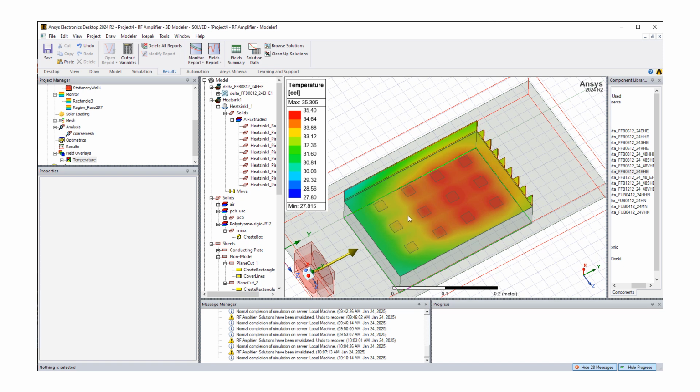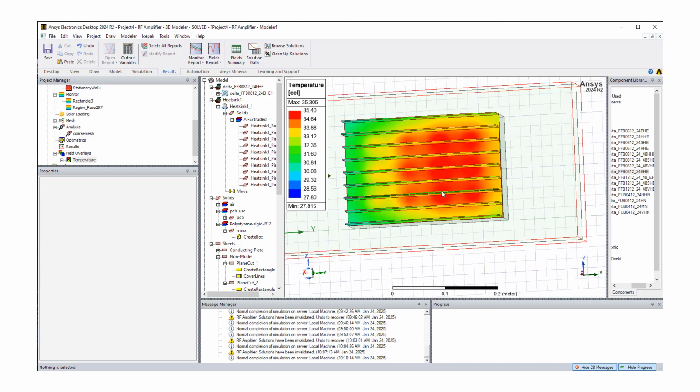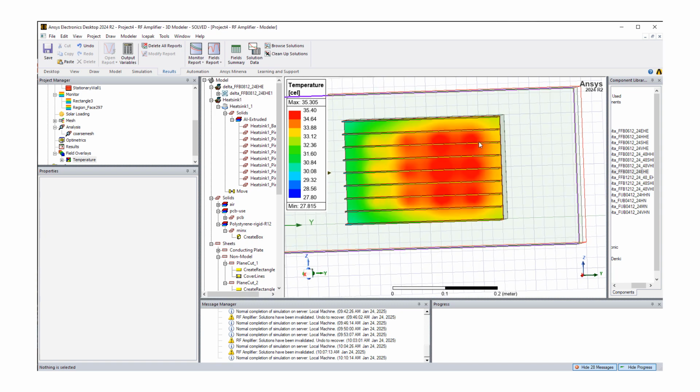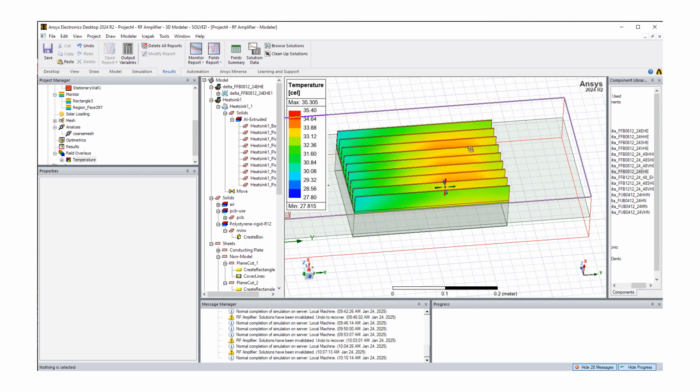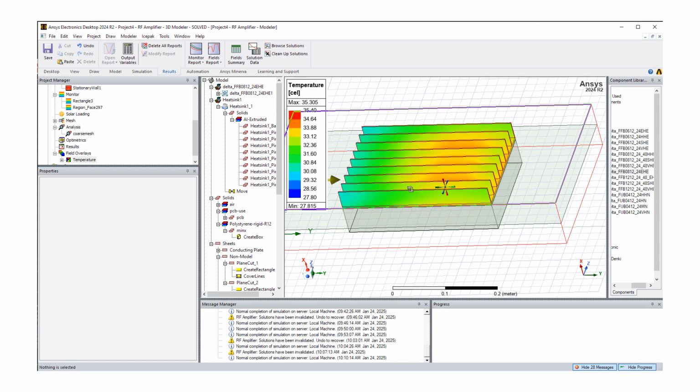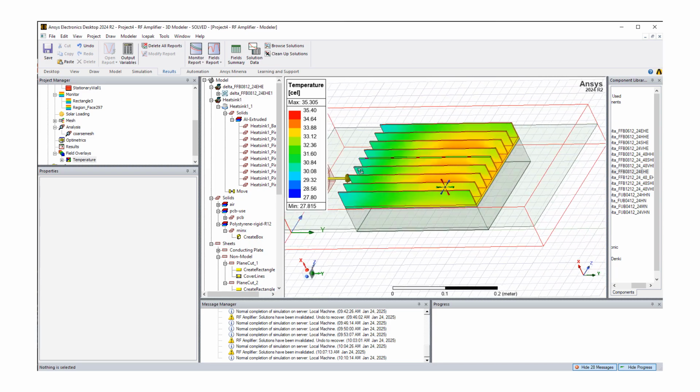And as we move away from the fan, and with the addition of heat, things are getting hotter in the y direction as it goes downstream, and we have the peak temperatures near those regions, and then that heat essentially is conducted away through the heat sink, and the convection essentially takes the heat away from the heat sink itself.